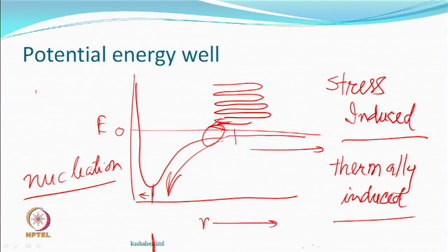That means, by giving the right opportunity, either stress induced, thermally induced, and another one which we also know as solvent induced. That is, you put the fiber or whatever polymeric material in a proper solvent, which does the same thing as the thermal energy may do, and that can also give you solvent induced crystallization.